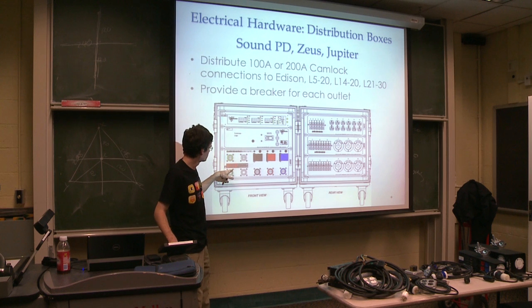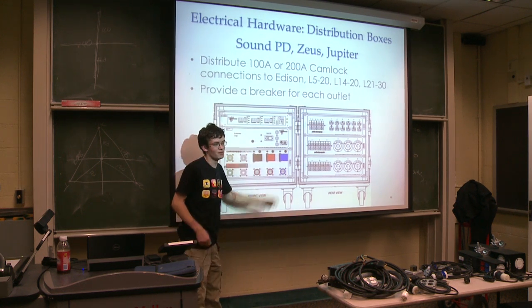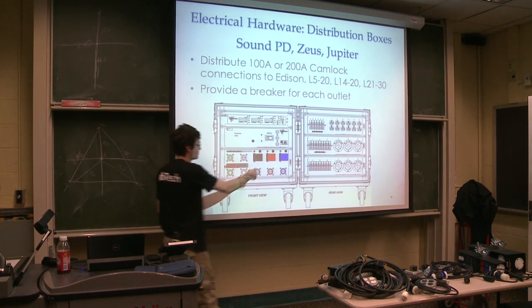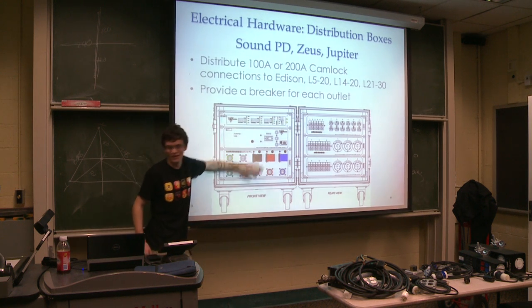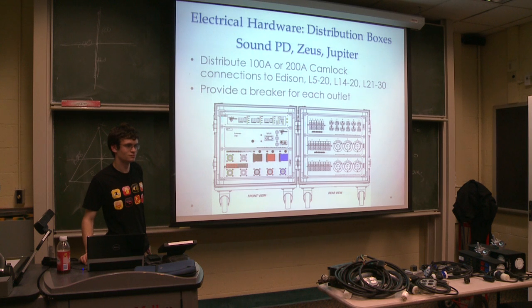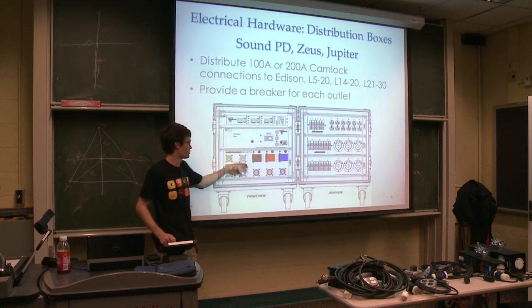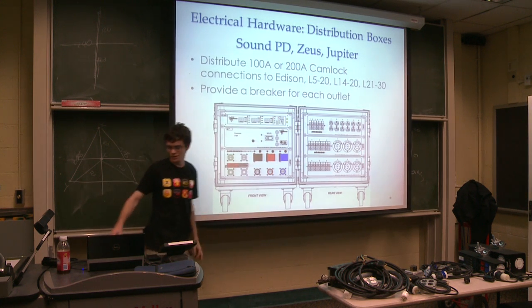They actually have little probe ports along the top row here for sticking a multimeter probe into. So you don't have to stick your multimeter probe into here when it's connected, which is a bad idea. There's a reason these are covered. Something else to be aware of on that, the main breaker doesn't shut off the other row of Camlock connectors. Yeah, these are hardwired through, so this is a safety breaker for this stuff.